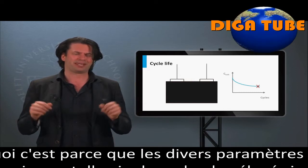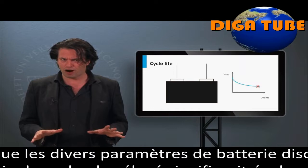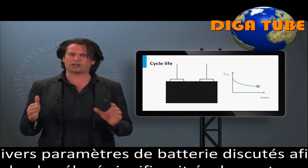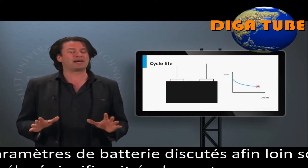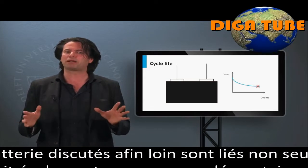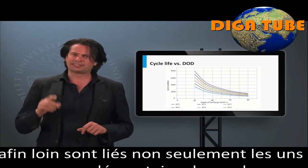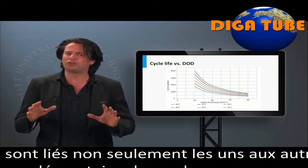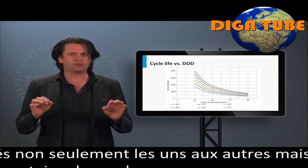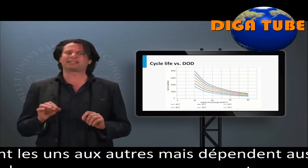Why? It's because the various battery parameters discussed so far are related not only to each other, but are also dependent on temperature. Let us discuss this interesting interplay of the battery parameters. Now, the cycle life depends heavily on the depth of discharge until which those charge cycles last. Also, it depends on temperature.